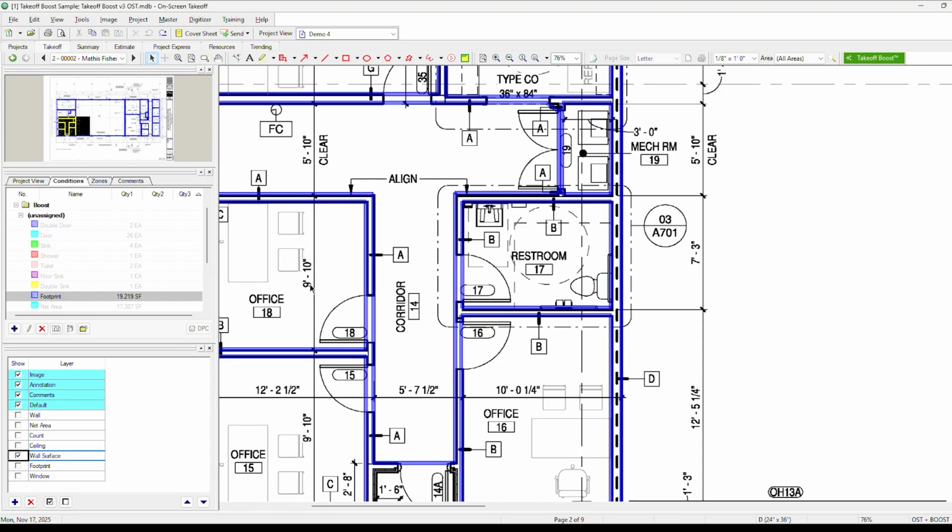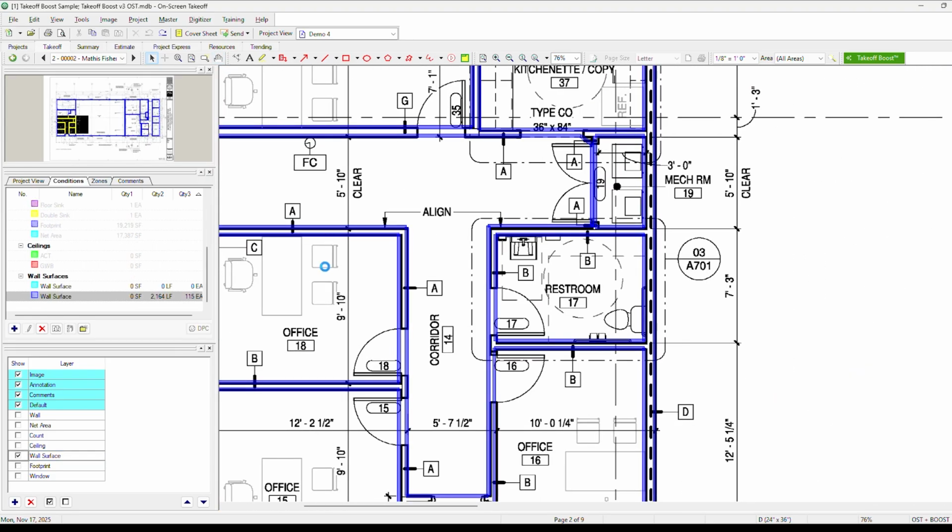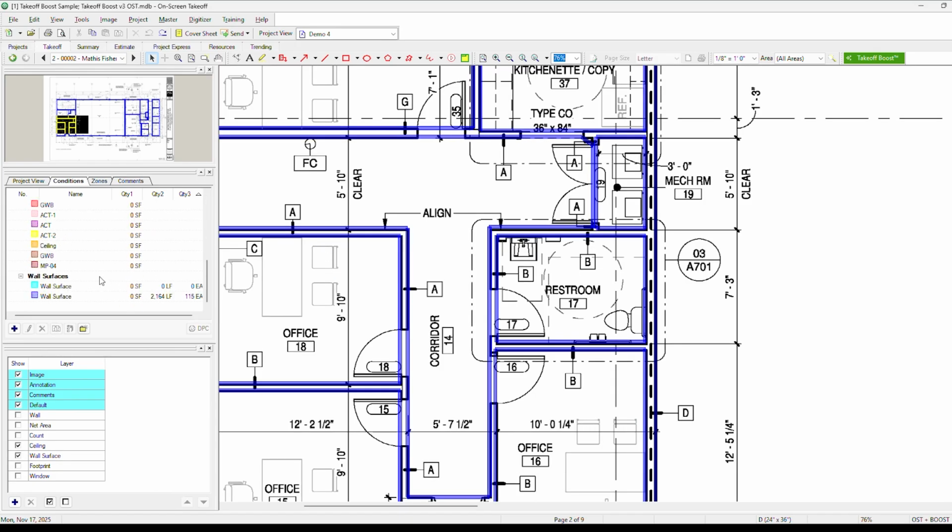So you can see I'm getting single sides of each one of the rooms here. If I click into this, you'll notice that we've also defaulted in the quantities. So surface area, single-sided as our quantity 1, your length, so you can get just the regular length of it, as well as segment counts for things like counting corners. And you can easily reassign these results too.